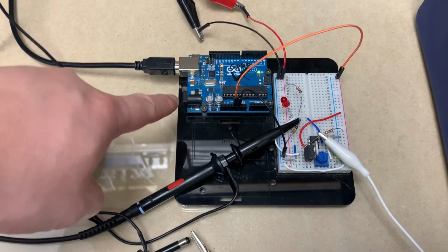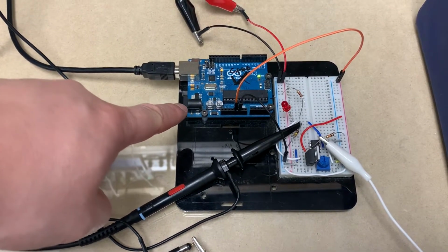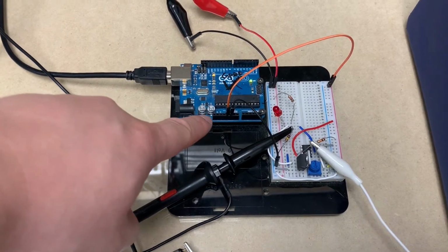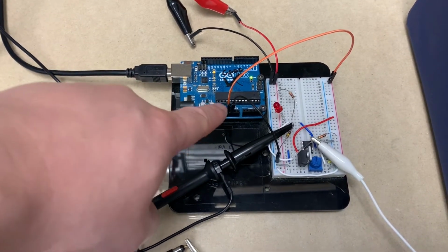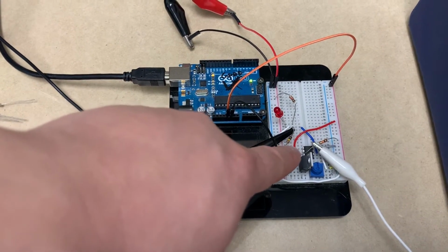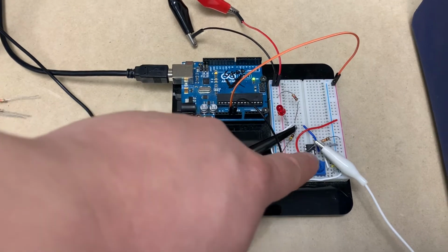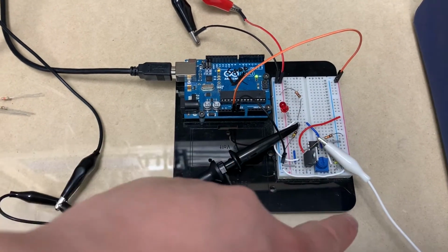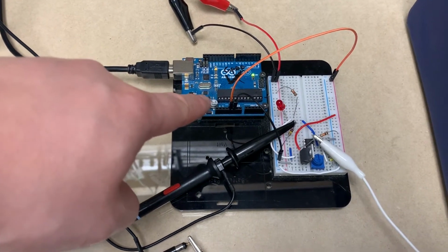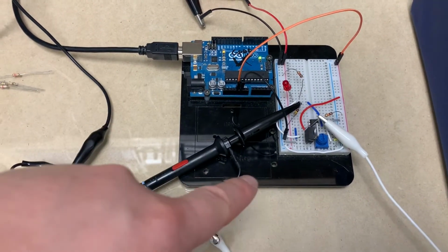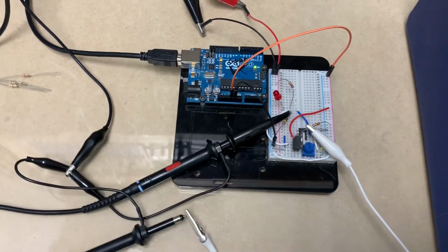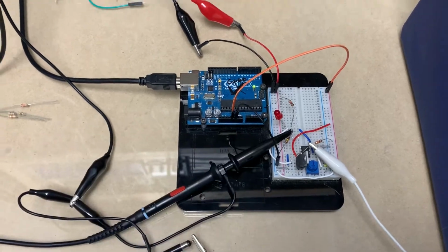But right now we're not going to use the Arduino to read the digital voltage yet. We are just going to use it to provide 5 volt to our comparator so that it can operate, but later we are going to feed this signal here to the Arduino so that it can actually do some counting. Okay, so right now I have channel 2 hooked up as the signal output from the comparator, and signal 1 from before is going to be from the SPAD.